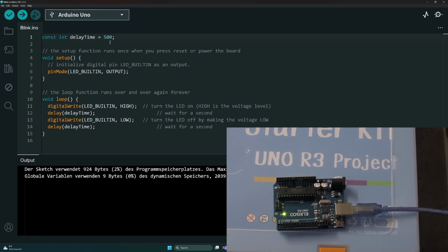And this random word basically gets optimized away by the compiler. The volatile that I had in previously tells the compiler, you don't know what's happening here, so just leave it untouched. However, this const sees that it's used the same way as this LED built in, and it is optimizing that away into a constant. However, it could be different.